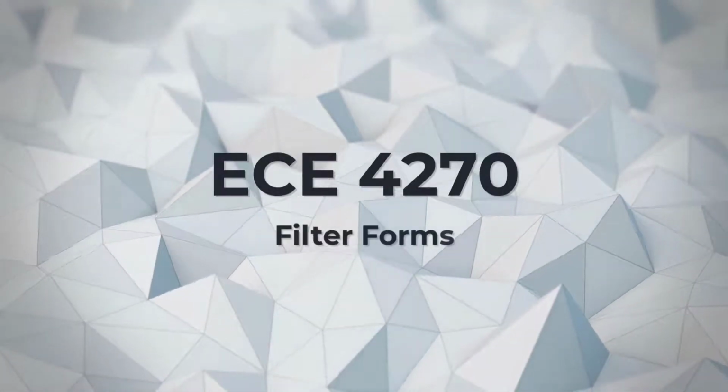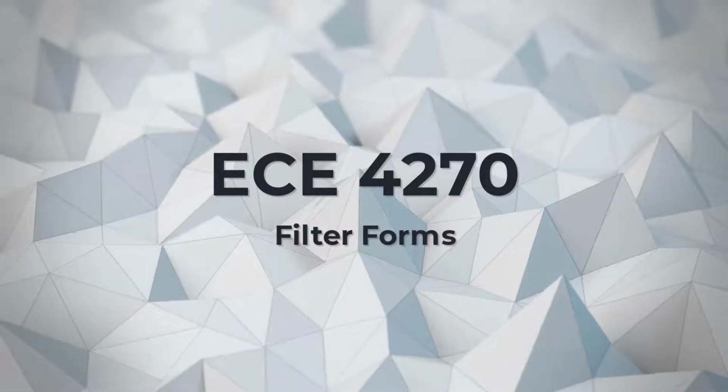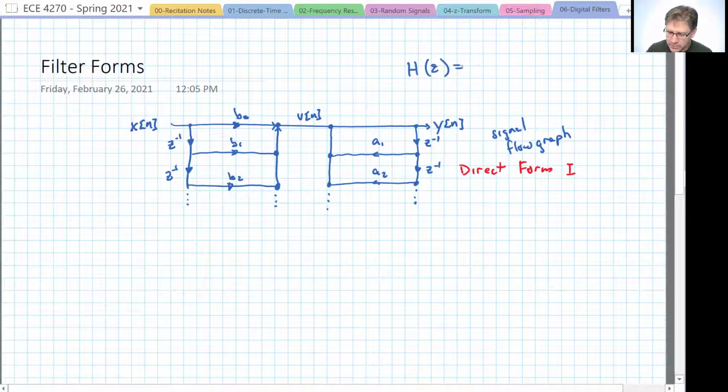So we finished last time with a discussion of block diagrams and finally signal flow graphs, and we put down the direct form, direct form 1 actually, signal flow graph to implement a difference equation filter. Well, this is a direct implementation of the filter as factored with H(z) equal to H_p(z) having the poles and H_z(z) having the zeros.